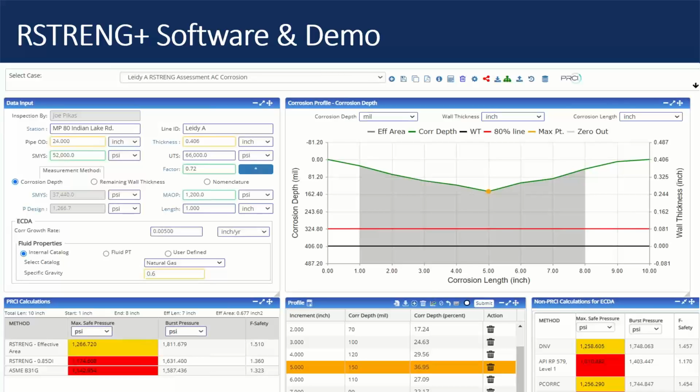And unfortunately, or fortunately for the US, either way you can look at it, we have a variety of interaction rules because there are no regulations on them, except ASME B31.8 and 4 that you must use interaction rules a minimum of 3T and 3T, and many companies determined that they wanted to go the route of 6T and 3T.